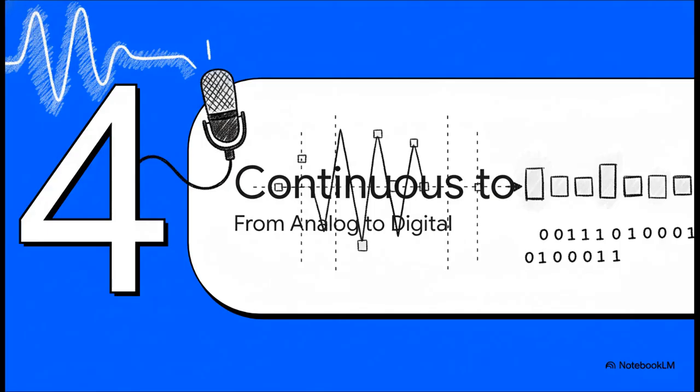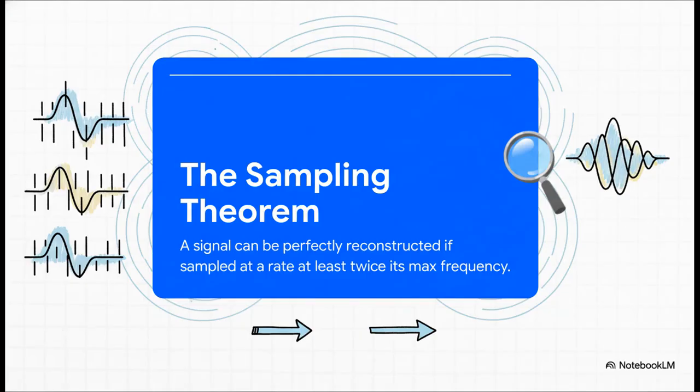This brings us perfectly into Section 4, from continuous to digital. How do we take the smooth, analog reality that's all around us and convert it into the ones and zeros the computers actually understand? The entire digital world is built on one kind of mind-blowing idea, the sampling theorem. It says that as long as you take snapshots of a signal fast enough, and fast enough means at least twice its highest frequency, you can perfectly rebuild the original signal later on. No information is lost. It's like knowing you can perfectly capture the motion of a helicopter's rotor blades as long as your camera's shutter speed is high enough.